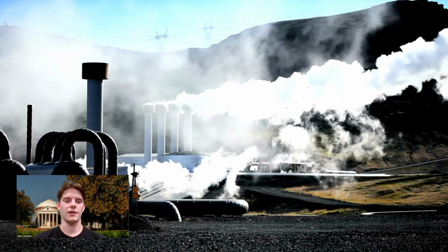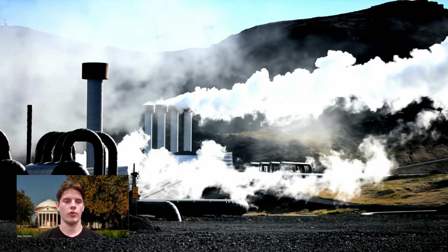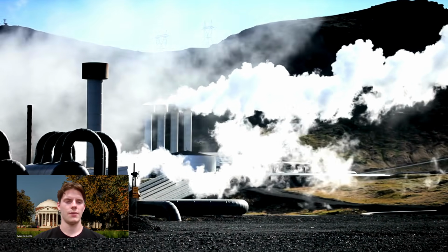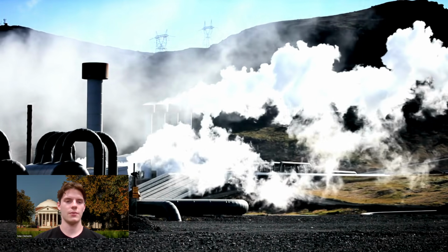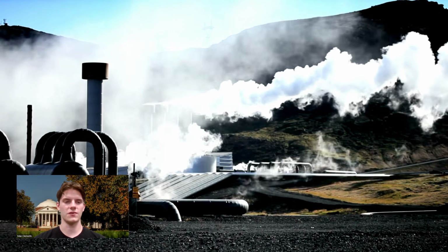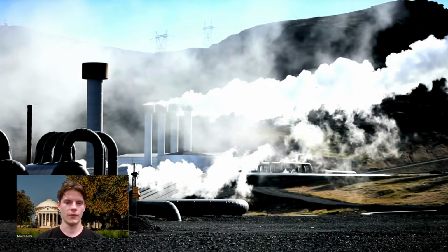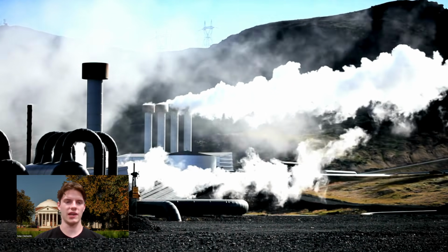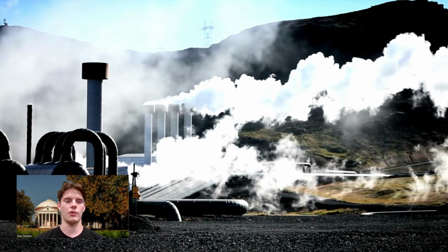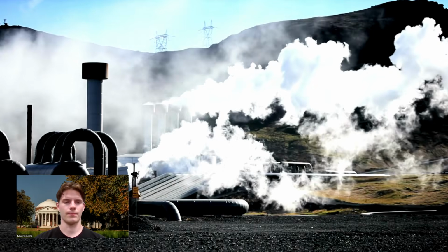The geothermal gradient is the bedrock of geothermal energy exploration. A high geothermal gradient means that economically viable temperatures for electricity generation, typically over 150 degrees Celsius, can be found at shallower, more accessible depths. This significantly reduces drilling costs and complexity, making projects more feasible. Conversely, in areas with an average gradient, reaching those temperatures might require drilling to depths of 5 to 7 kilometers or more, which is considerably more expensive and technically challenging.